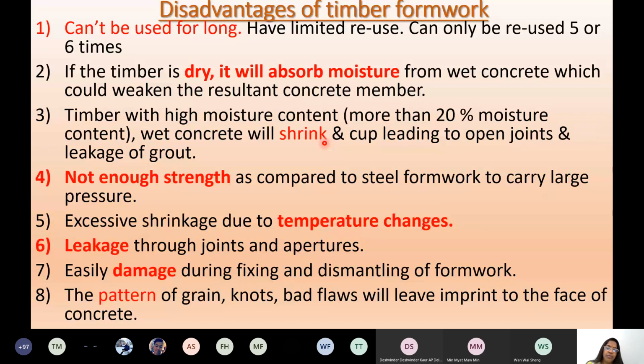There will be a gap between the layers of the wood, which has to be fixed before you pour in concrete. Not enough strength as compared to steel formwork to carry large pressure. Yeah, it has a reasonable strength, not a very good strength. So you cannot use it for very heavy loads like high-rise buildings,